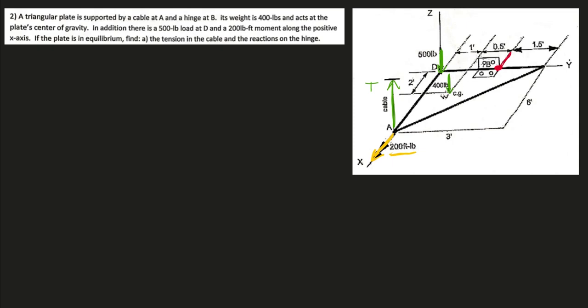So the hinge is gripping at this point, which means the hinge puts a force at this point. And this one force will have an x component, a y component, and a z component. And these are all unknown, so each one of these here is an assumption on my part. The direction, that is. I know that there will be 3 components for this one force, but the directions here are all assumptions. And here's that force in vector form.